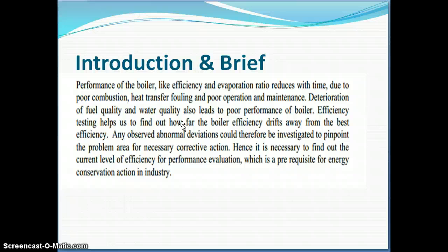This deterioration of fuel quality and water quality leads to poor performance of the boiler. Efficiency testing helps us find out how far the boiler efficiency drifts away from the best efficiency. Any observed abnormal deviations could therefore be investigated to pinpoint the problem area for necessary corrective action. Hence, it is necessary to find out the current level of efficiency for performance evaluation, which is a prerequisite for energy conservation action in the industry.